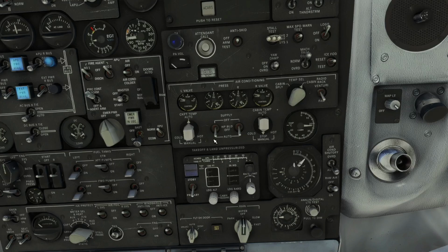But normally we want to just leave this in auto, and you can see they spring back, and they're just a little bit on the other side of warm for the mix manifold there. And that's how that works. You can see our supply temperature already dropped down to about 20. Now it's coming back up as the mix manifold does its thing. So yeah, in fact now it's overreacting because it was actually at the temperature it was trying to hold, and so we cooled it down a little much, and so now it's actually bringing warm air into the cabin, and you'll see that fluctuate as the cabin air changes and so on and so forth.